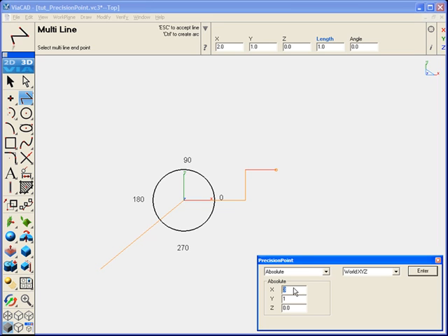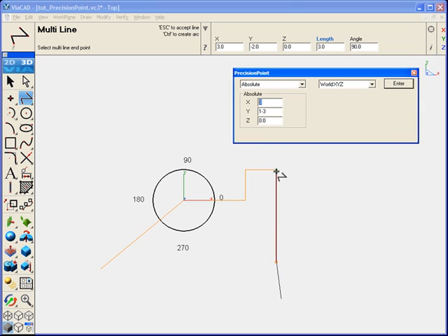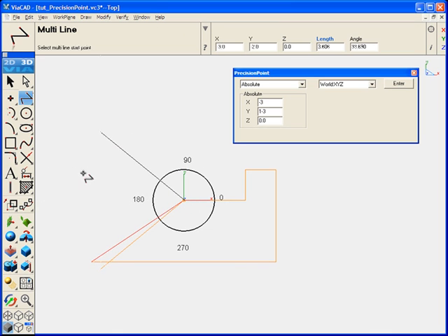and 3 for X. So as you work your way around with absolute coordinates, these are the coordinates defined in relationship with the actual drawing origin, 0, 0. Also notice you can plug in formulas. In this case, we've just put in 1 minus 3. We were 1 up, and we wanted to go down to minus 2. And at any point, you can also move your cursor and click to set a point.